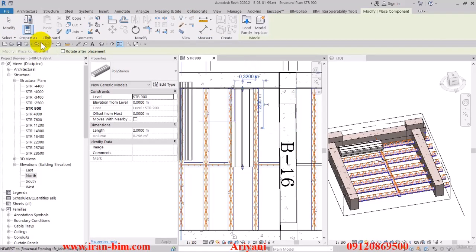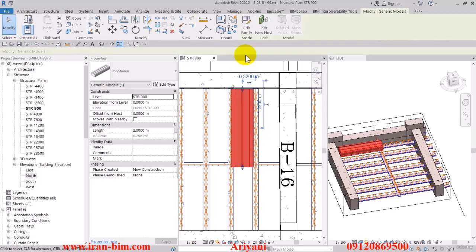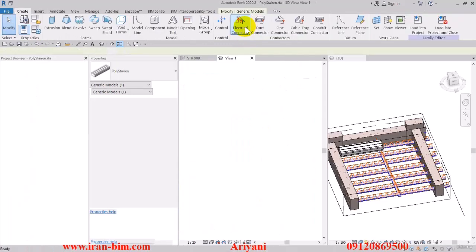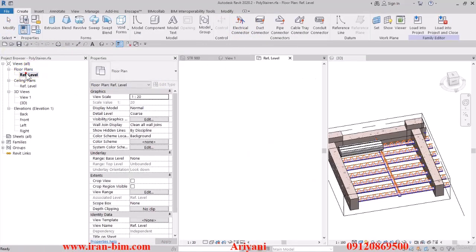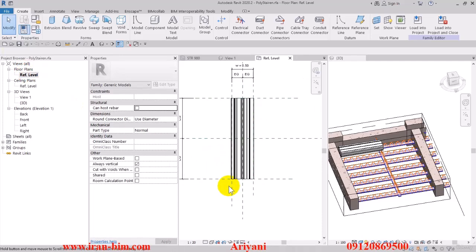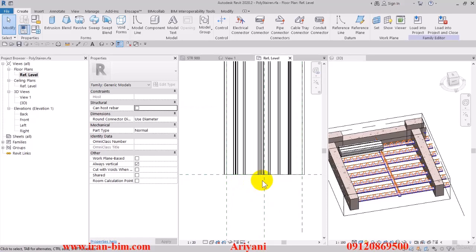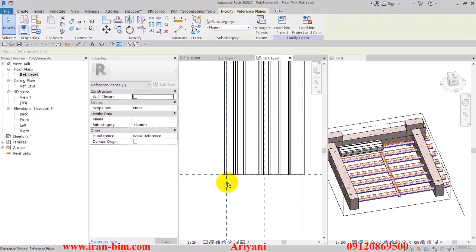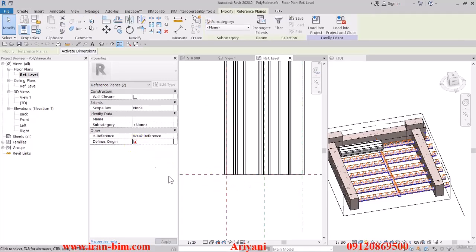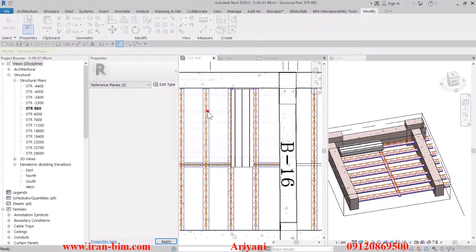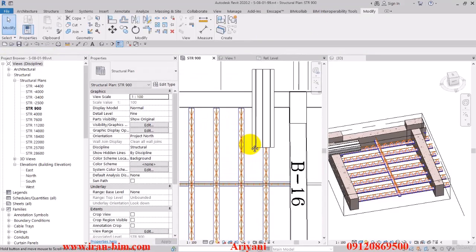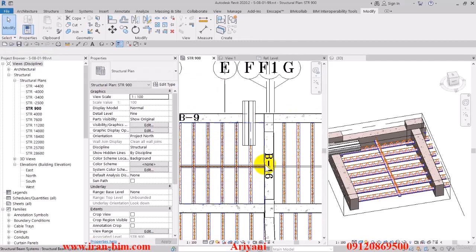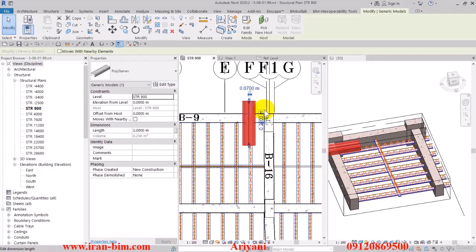And so in order to solve this issue, we can use a technique which involves going here. And if we take a look at this, let me zoom in. So we basically want the center point to be in the middle of the corner piece here. So we can put this on origin and then click on load into project. But remember to do this before you model next time, because changing the origin point will probably mess up your work.